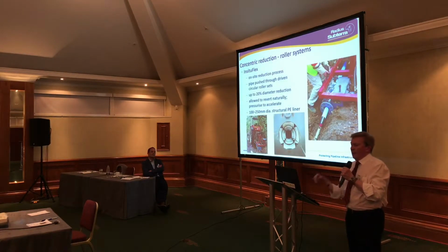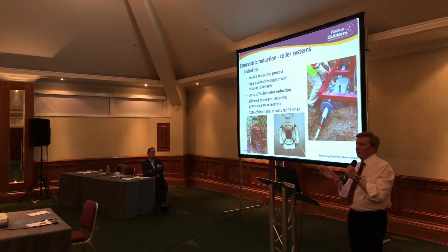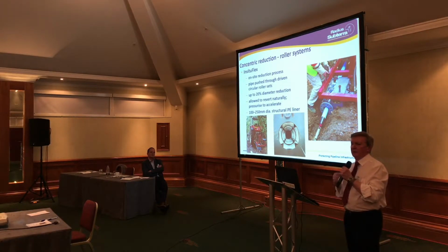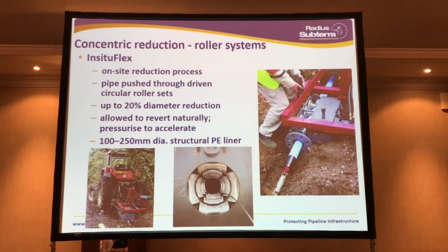In Situ Form had their own version of this technology called In Situ Flex, in which the process was carried out by driving the liner pipe through driven rollers. It's no longer available in the UK, but I think still is available. It's still used in North America. Size is 100 to 250 diameter.